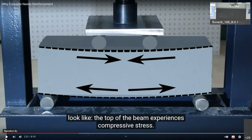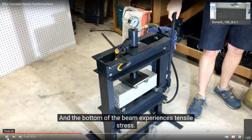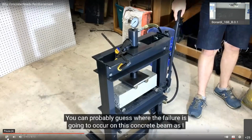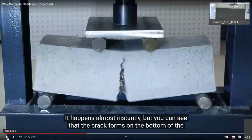Even if we have no horizontal force applied, this compression force is exactly equal to this tension one. The problem is that at the bottom we have tensile stress, and we have said, and now we are seeing, that concrete has no tensile strength.